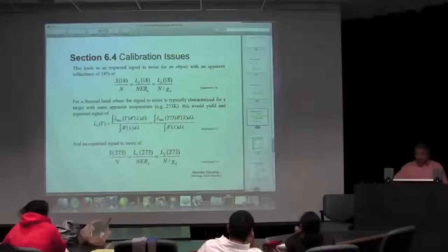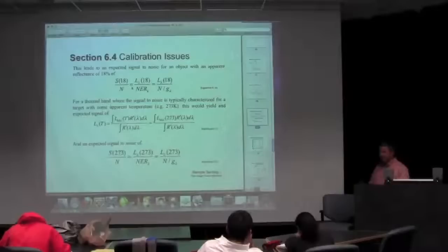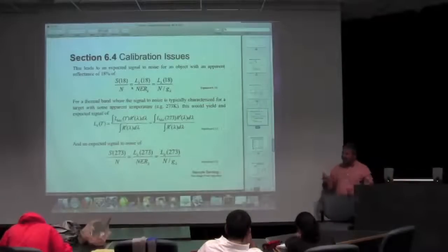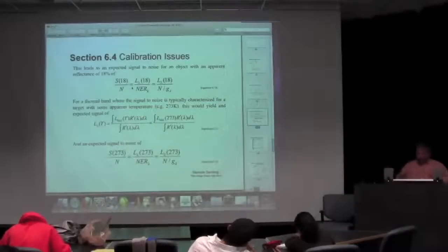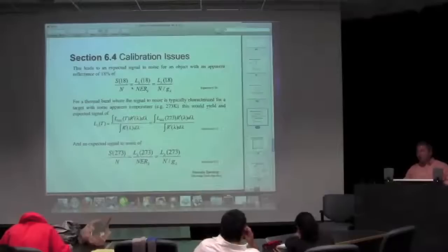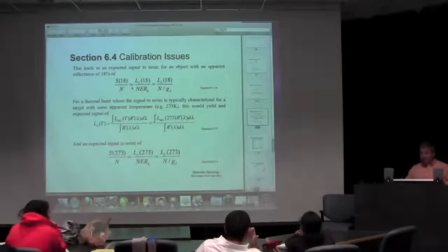Okay. For a thermal infrared sensor, you do exactly the same way, right? But typically you don't want to use dark current. Dark current in the sense of a thermal infrared sensor really is a very strange meaning. That means you're looking at an object that's at absolute zero, and that's typically not going to be the case. So what you want to do is look at an object at a temperature that's similar to the temperatures that you're going to be measuring with that detector.